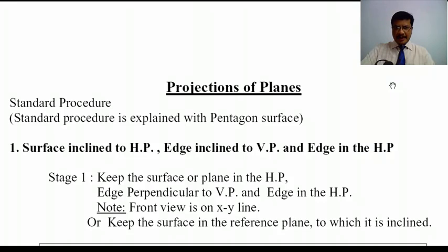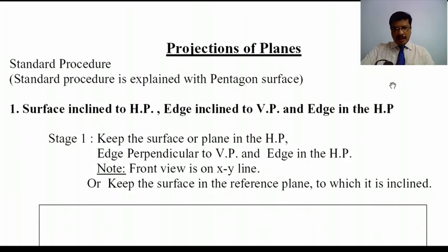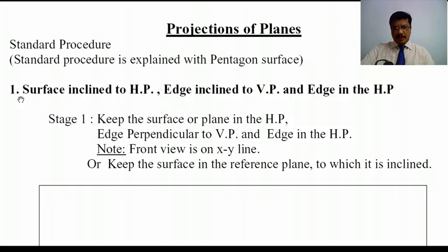Projections of planes. So here this is the standard procedure for solving any planes problem. All the planes problems we can split into 4 cases. Here I am showing the first case. In this first case, surface is inclined to HP, edge is inclined to VP, and the edge is in the HP. This is the first case.